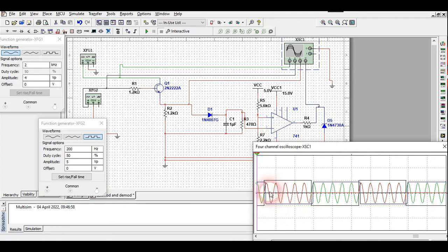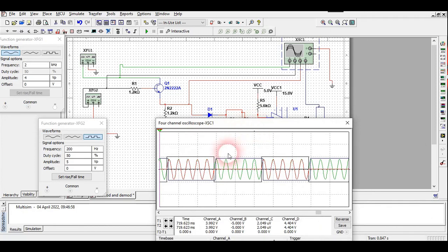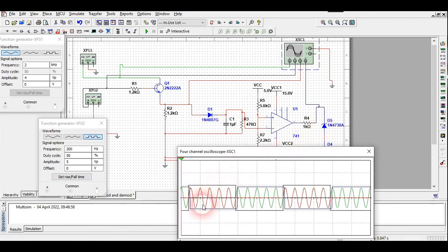So the reason is that this op amp is used as an inverter. That's the reason that both signals, the baseband signal and the demodulation output signal, are inverted, okay. And we are getting the ASK part when bit high is present in the input and bit 0 is present in the output, okay. So I hope you have understood the reason why both of the signals are inverted and why we are getting the ASK output when the output of demodulation is bit 0.